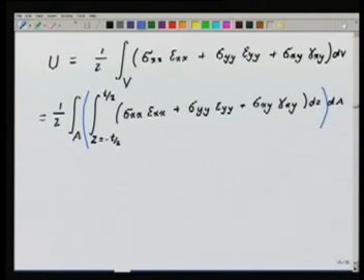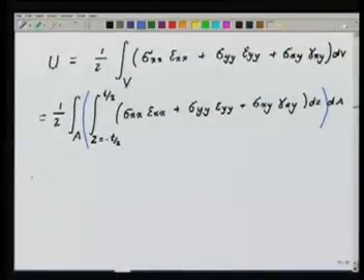Now, why are we doing this? Because we know the expansion of the UVW in terms of z explicitly. So we would like to eliminate that dimension, which in terms of our mechanics means that we are looking at equilibrium or the responses or the forces not in terms of stresses, but in terms of stress resultants, which are the moments, the shear forces, and so on. So this integral here we will get as half integral over the area integral over z,